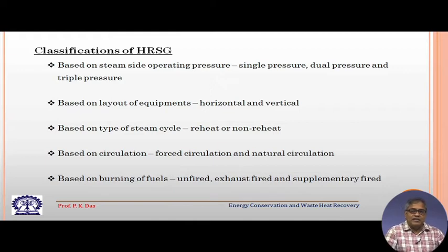Now, HRSG is very commonly used in connection with the gas turbine, steam turbine, steam power plant combined cycle. Now, there are many variations of HRSG. Based on the steam side operating pressure, it can be described as single pressure, dual pressure and triple pressure.